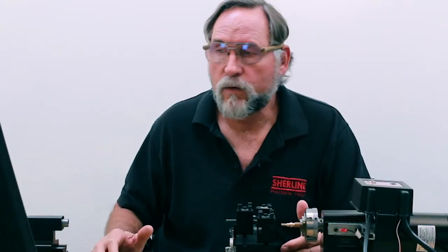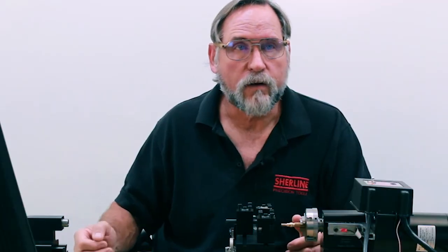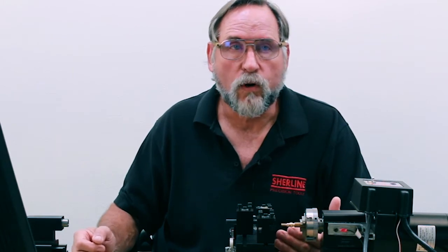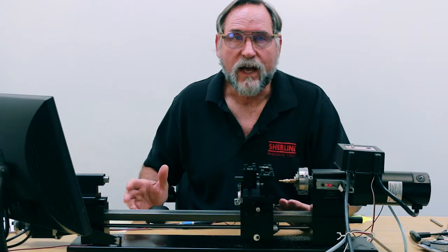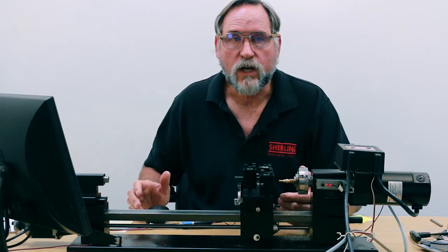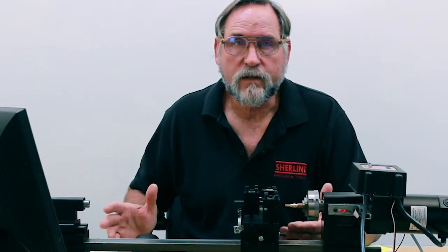Okay, at this point we have each of the small programs dialed in. What I would do now is take the flash drive out and cut and paste one program after the other and merge the files into one long program. Then we're ready to start mass producing these parts, but it's a lot easier to go through one small program at a time for each operation. As far as editing and rerunning everything goes, that's how I do it.